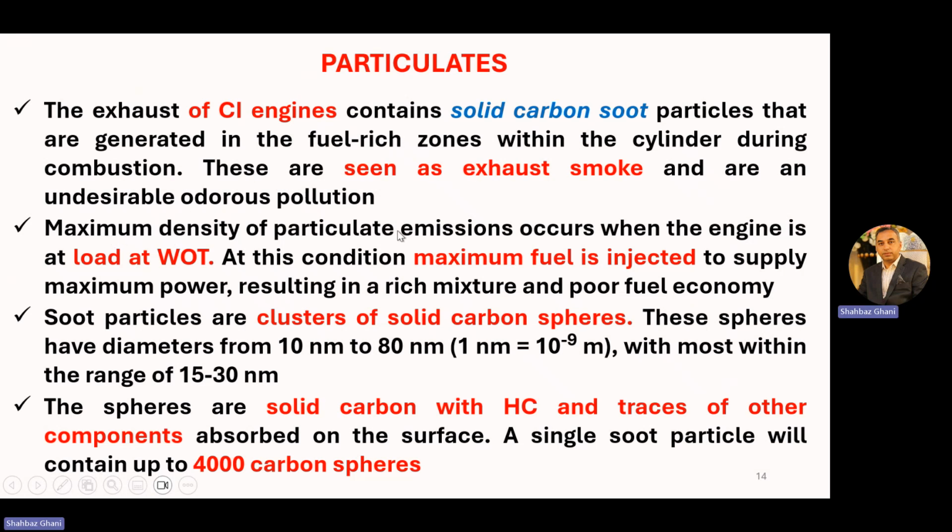Maximum density of particulate emission occurs when the engine is at load at wide open throttle. At this condition, the maximum fuel is injected to supply maximum power because we are getting the maximum amount of air, resulting in a rich mixture and poor fuel economy.